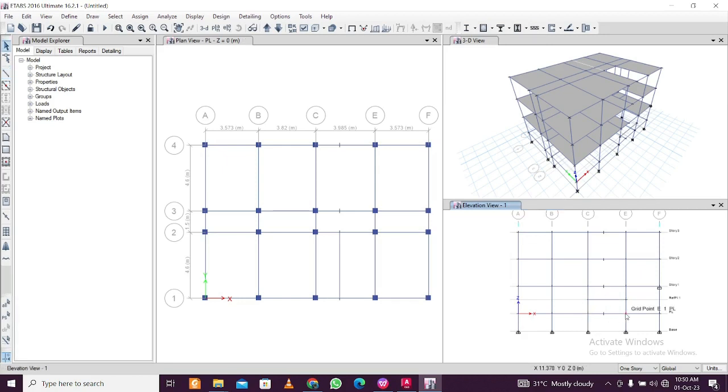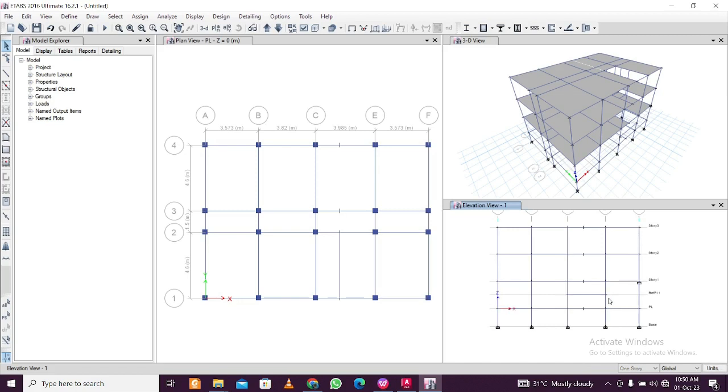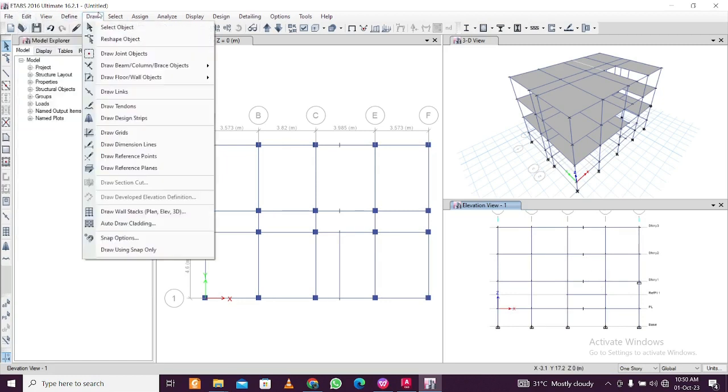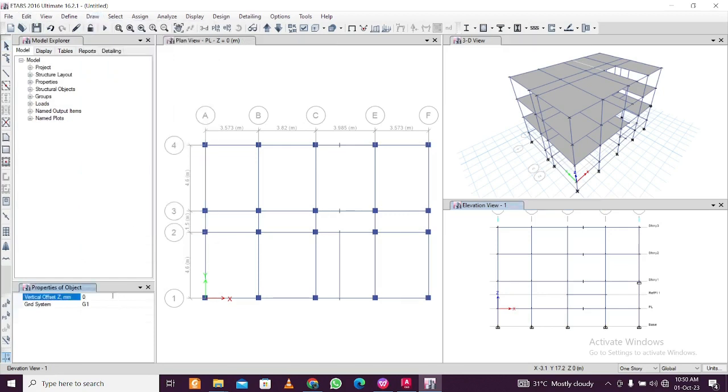Once this is done, you can then copy to the other reference plane as well. It's better if you just create the reference planes in one go. Go to draw, and go to reference planes, and here 1500, this is in mm, right? So 1500, and then we create a reference plane here and a reference plane here. Then we can easily go with the thing here, click on escape, and again take this.